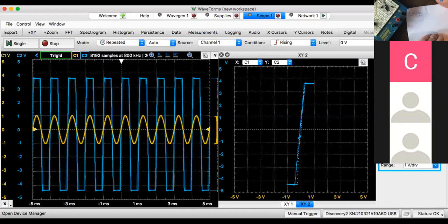The output can never be bigger than positive 5 and negative 5. So right now, the output is trying to be positive 11 and negative 11. There's no way you can get an output of positive 11, negative 11. And the maximum you can reach is, look what we have here, positive 3.7, negative 4.5. So that is the maximum positive and the maximum negative.